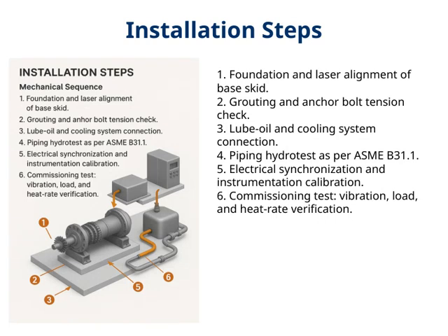Now, let's walk through the key installation steps to ensure everything runs smoothly. First, we start with the foundation and laser alignment of the base skid. This is crucial because a precise foundation sets the stage for the entire system's stability and performance.